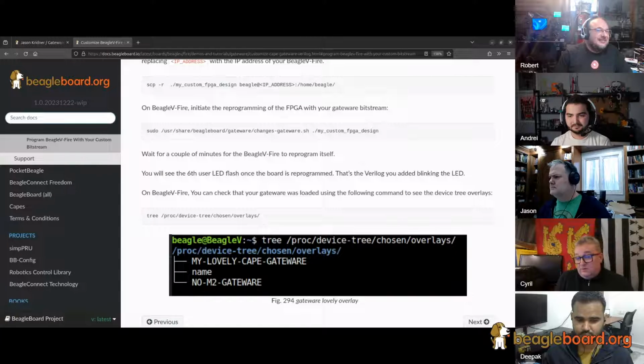because the PolarFire SoC FPGA is a flash FPGA, so it doesn't really follow the model of the other ones, which are SRAM based. So we don't fit in the standard FPGA manager approach. Connor did something else that will be even cleaner.